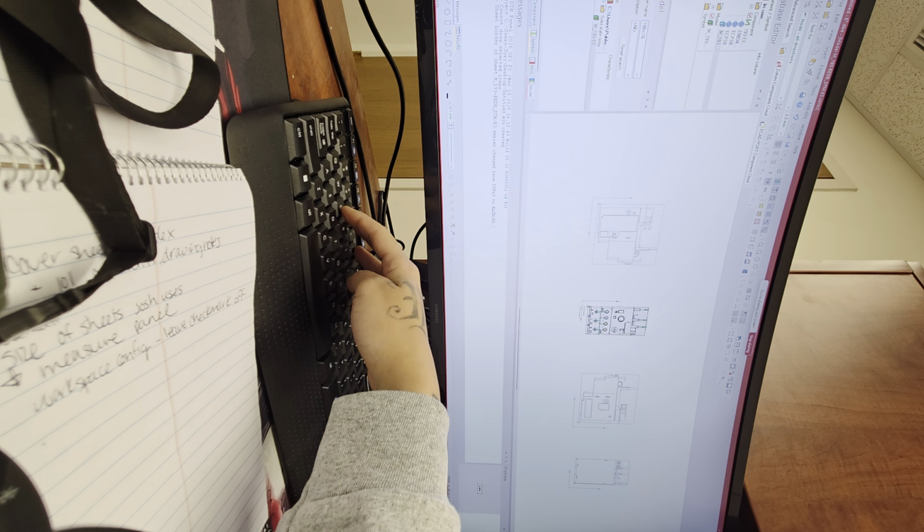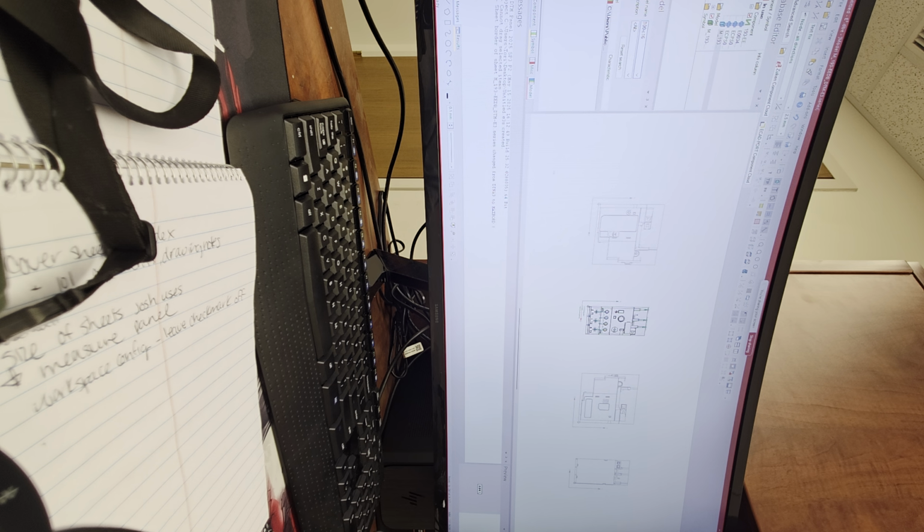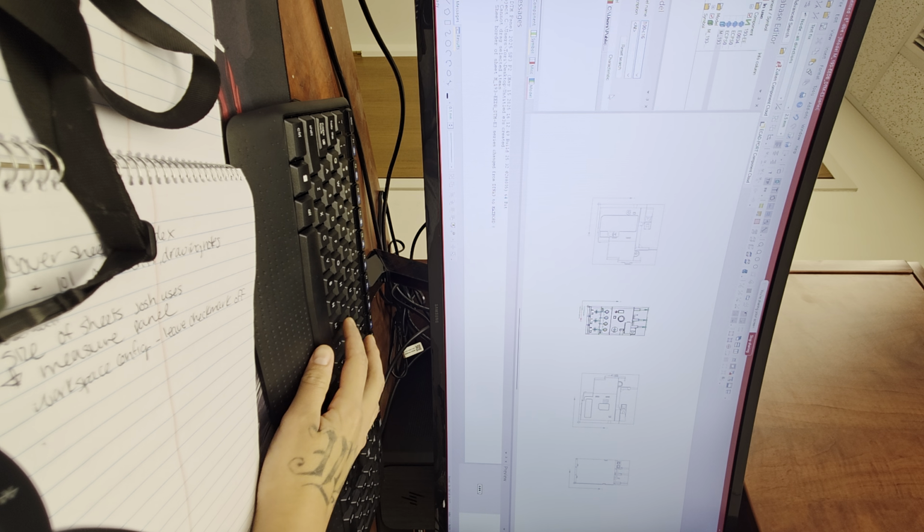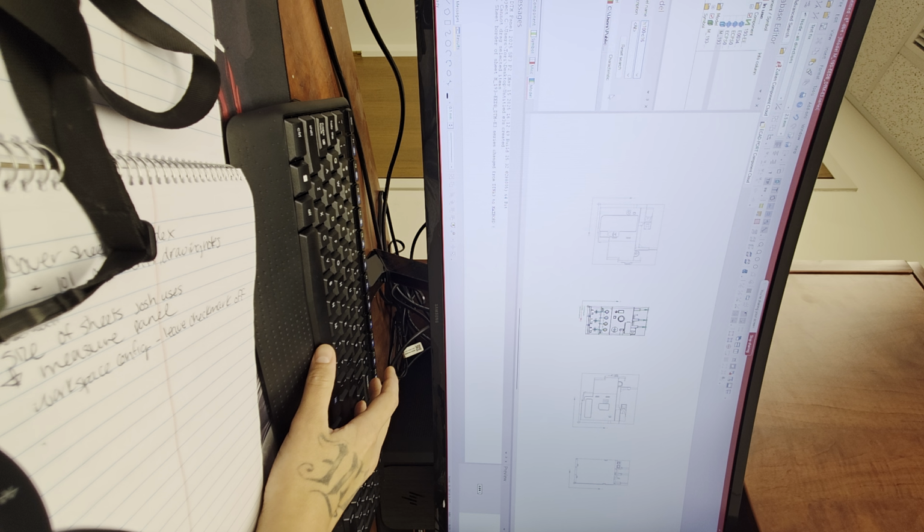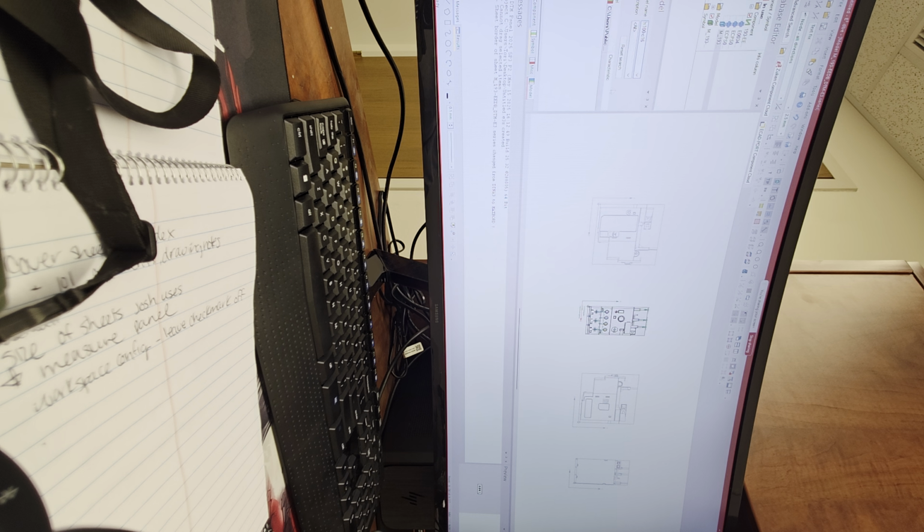Even a couple characters will do. Oh really? Just put a wild character after it. Even if you just type in like 100 wild character. And also with just models in general, a lot of models have an M prefix, like M underscore and then the part number. So whenever you are searching for anything, I would just generally say part numbers or models or symbols, etc. Always put a wild character in the front and a wild character at the back. That's how the search actually should work.